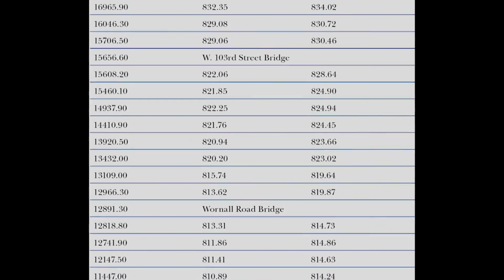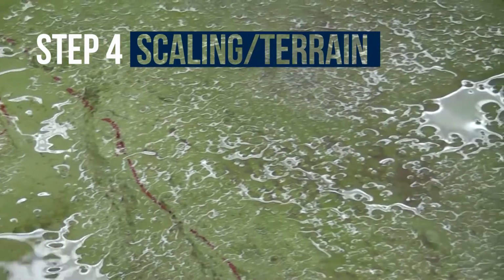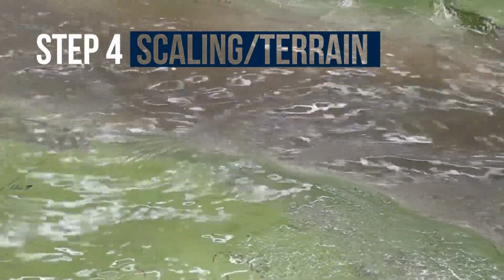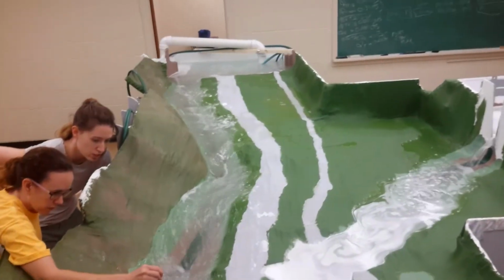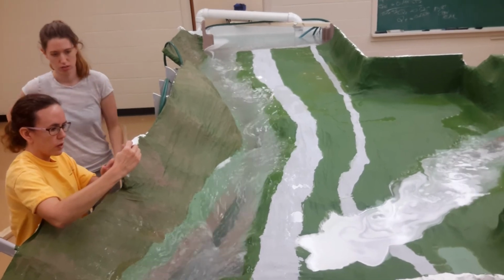Okay. So as we begin our physical model development, the steps that we have to go through have to do with the scaling considerations. And once again, like I said, we want to create a model that is large enough that it accurately depicts the flow patterns and the flow depths and the velocities, but not so large that it's cumbersome and we need extremely large areas to build it or extremely large pumping plants to pump water through it. And at the same time, we also don't want it so small that we actually start getting into other hydraulic characteristics that will actually affect all of those other parameters we're looking at.